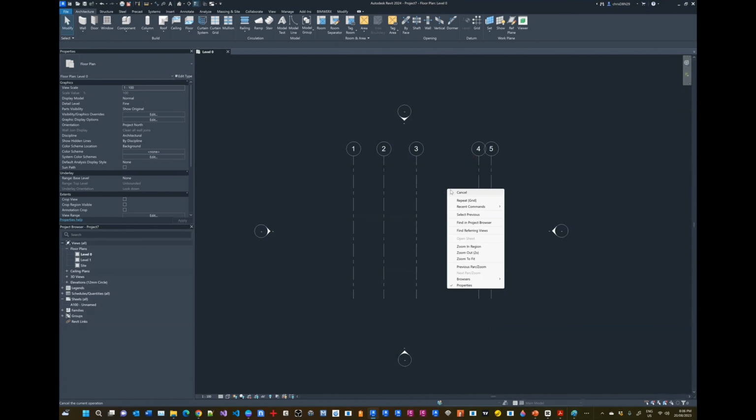And you can see, as I did in the first exercise with the test drive, I'm selecting everything here by doing a cross selection rather than a box selection. And then I am clicking and dragging these grids just to position a little bit more centrally in my model. And where is center? Center is where these elevation markers, if I had to draw a line between them, intersect. Okay, so more or less there. Doesn't have to be perfect.